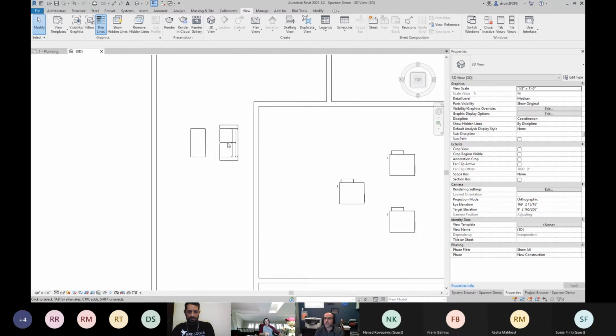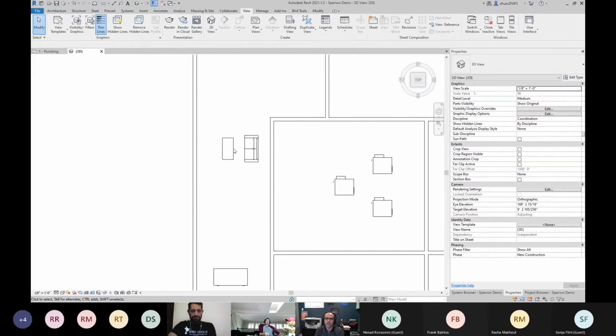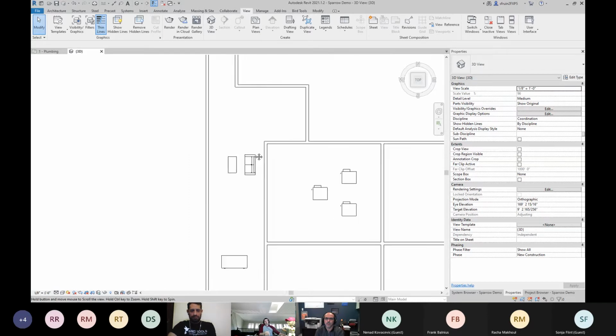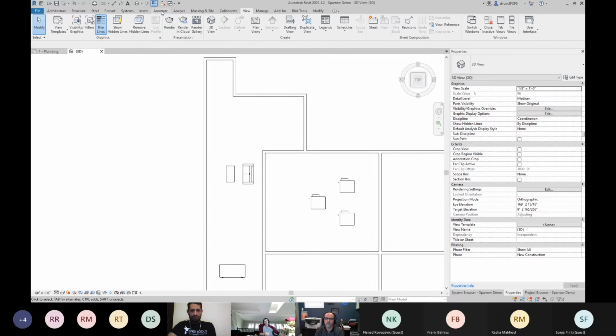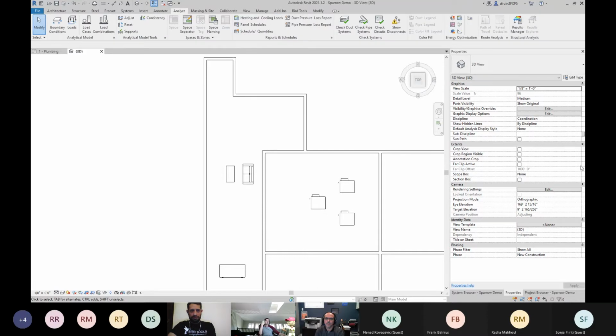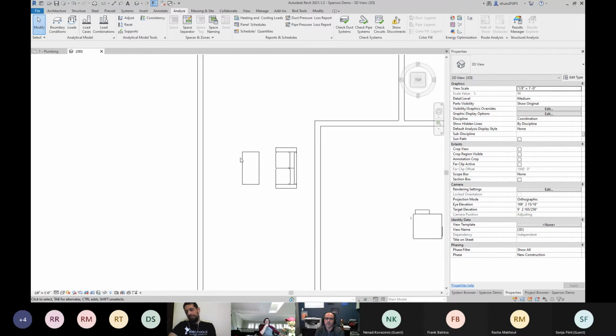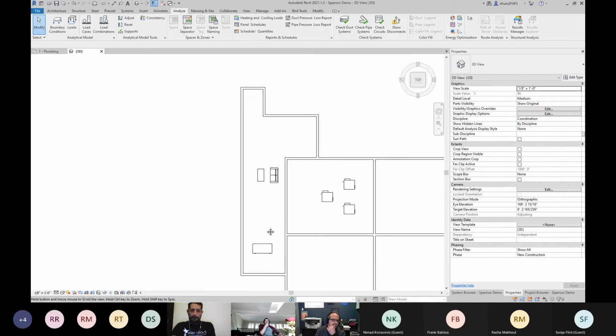And the idea with the couch, or this coffee table for example, is you could select this coffee table and shoot a ray bounce to this wall, and then shoot a ray bounce to that wall, and now we have a line. So now we can maybe find the center point of the line and build a grid around that. And why you'd want to do this is because architects a lot of times make really big rooms. So if you collect the surface of a really big room, it's hard. You couldn't place a simple rule for placing a grid of lights in this living room if this whole space is one space.